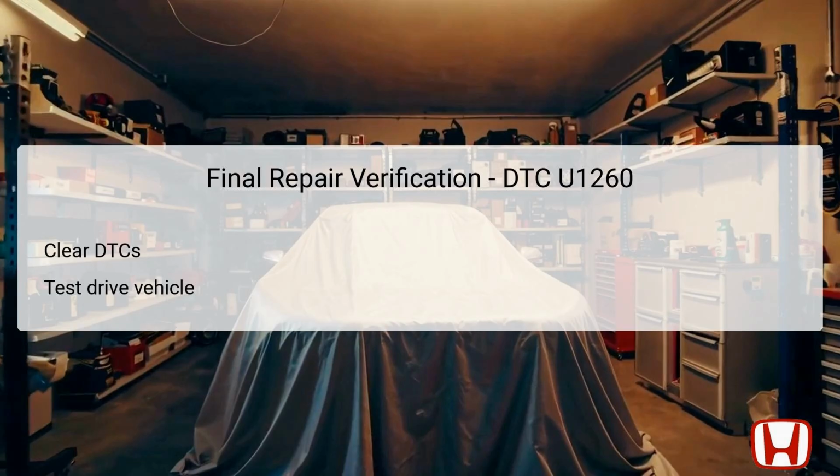This test drive is crucial as it allows you to observe any potential transmission anomalies that may suggest lingering issues. Pay attention to the responsiveness of the transmission and ensure that the auxiliary transmission fluid pump is engaging correctly during driving conditions. A successful test drive without the recurrence of the U1260 DTC will confirm that repairs have effectively addressed the underlying problems.